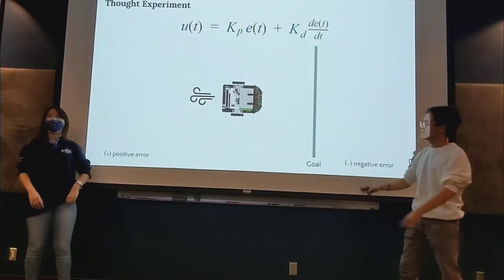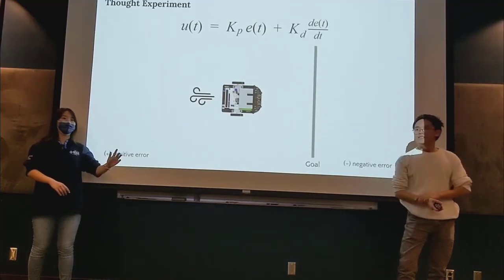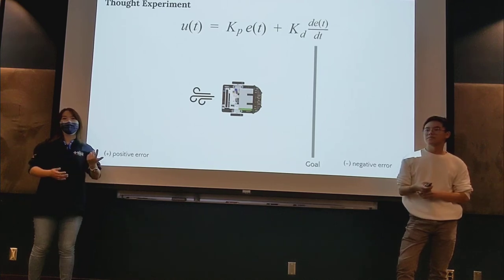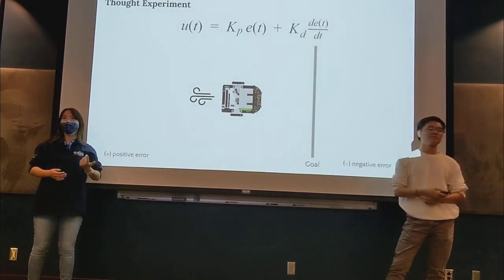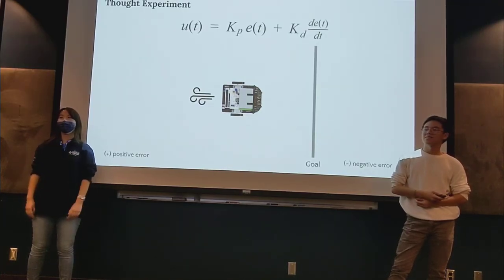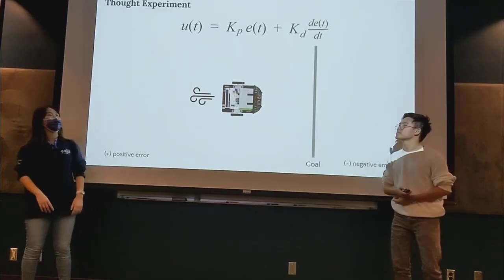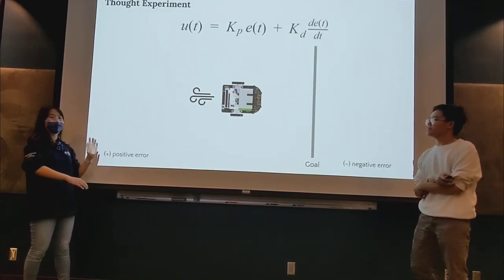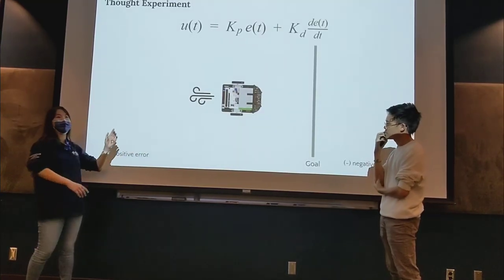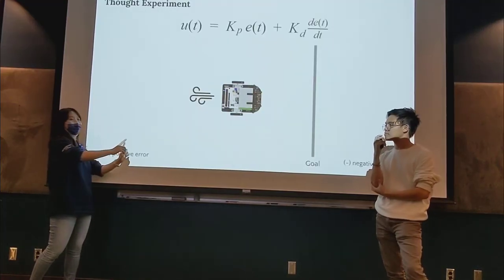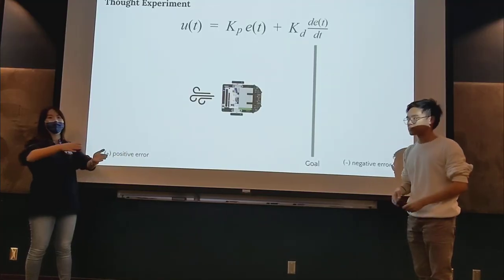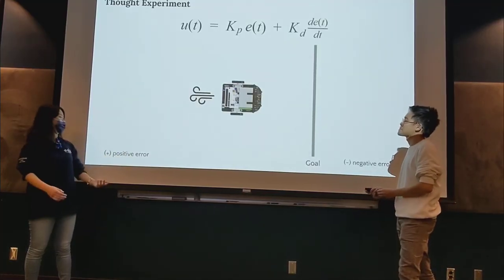Now, as we're moving towards our goal, would someone like to answer if the error is still positive or negative or 0? Positive but small. And how about the derivative term? Negative, I think. So you can note that our error term has gone from a big error on our previous slide to a smaller error now, and our derivative, since we are decreasing our distance to the goal, is negative. So it is rapidly approaching our goal and being dampened to slow down, to try to not overshoot.